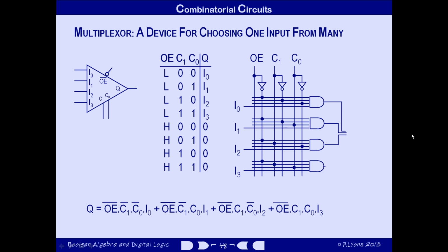Remember that I said that I'd explain about the output being labelled Q. Digital circuits are usually constructed as integrated circuits, which are built out of transistors. In circuit diagrams, resistors are identified by the letter R and an ID number, capacitors are identified by the letter C and a number, and transistors are identified by the letter Q and a number. T was already in use for something else, transformers in fact, when transistors were invented.